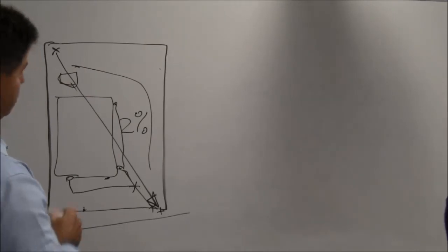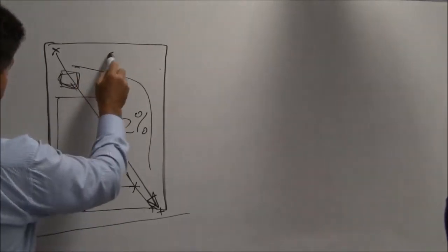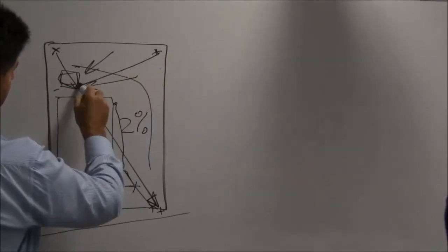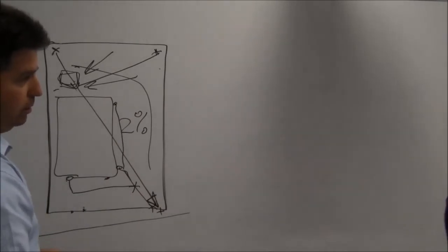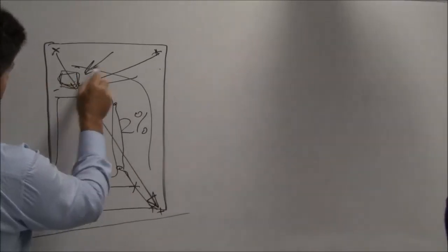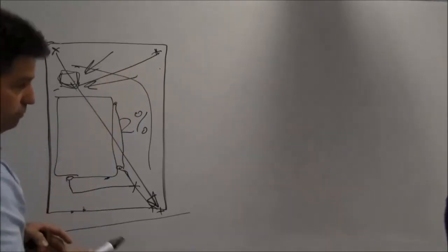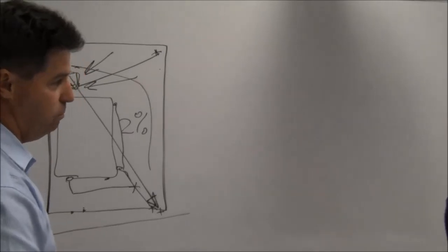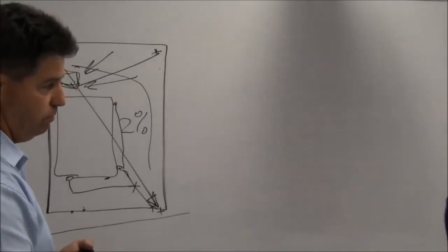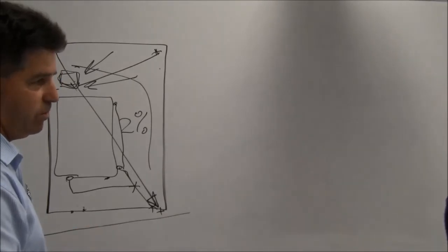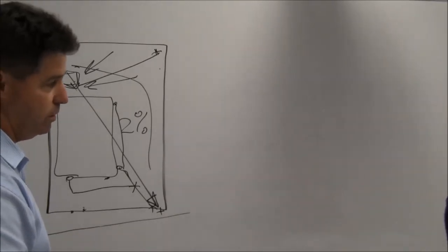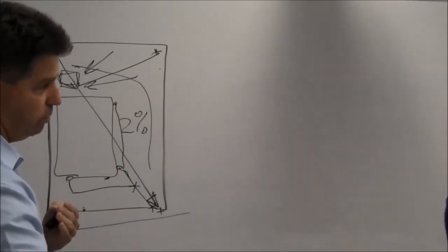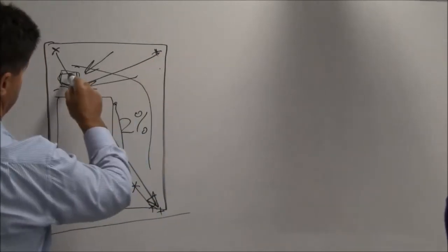So if we had a graded inlet pit here and we have water coming in from all directions into the pit, our time of concentration could be from here into the pit and then the time it gets out into the system. Basically by the time the water lands on the ground, it has a fraction impervious of what could be grass or thick grass, which is just the flow off the type of surface that it's on. If it's thick grass or landscaping, then it's obviously going to take a lot longer for that water to get to a point, from A to B to get to the pit.